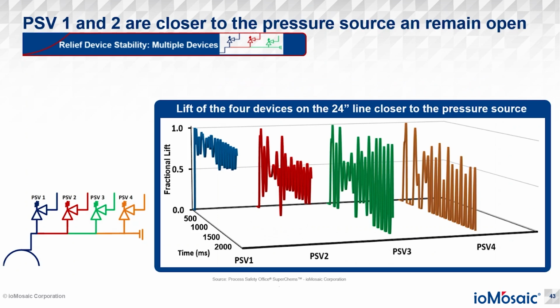And my reasoning for this is, as they're all bundled up, the pressure waves actually all become too coupled as they're too close together, causing this instability. It's almost like they're all kind of playing off of each other. So one PSV affects the other, and you've got strong coupling between these PSVs, causing PSV3 and PSV4 to really chatter, which causes a huge problem. So again, the 1D gas dynamics, the new features in 11.6, allow us that greater malleability to optimize our systems for stability and to improve stability.